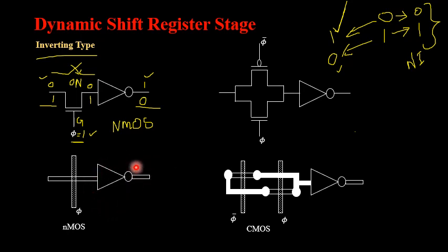So you can just replace this inverter with the NMOS inverter stick diagram. If I replace this with the NMOS inverter stick diagram, then this entire diagram will be called a stick diagram. Now it is called a stick diagram plus circuit diagram because it is considering the logical gate of NOT.